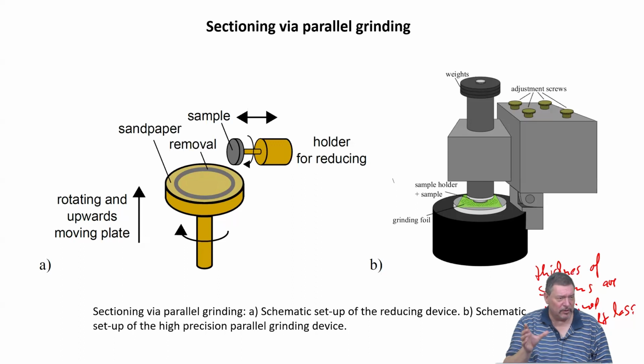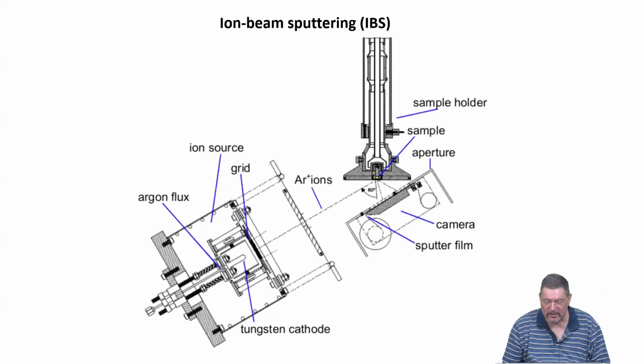Still, the sample will be totally weighed, and the sample is probably up to a weight of 2 to 3 grams. So there are not so many microbalances which can do this job. So you have to pay a little bit more to get a good one. But then it's a very simple and reproducible method to measure the thickness and again do these tracer analyses.